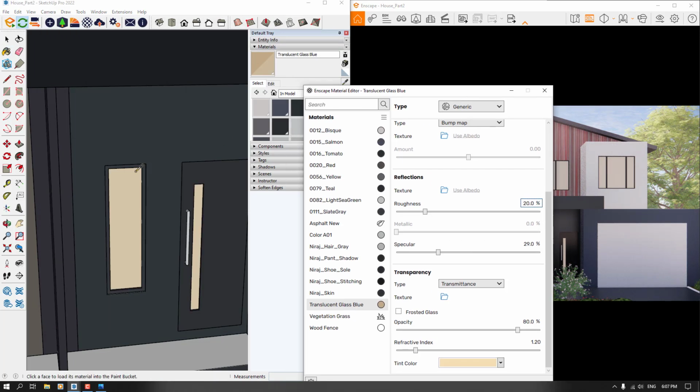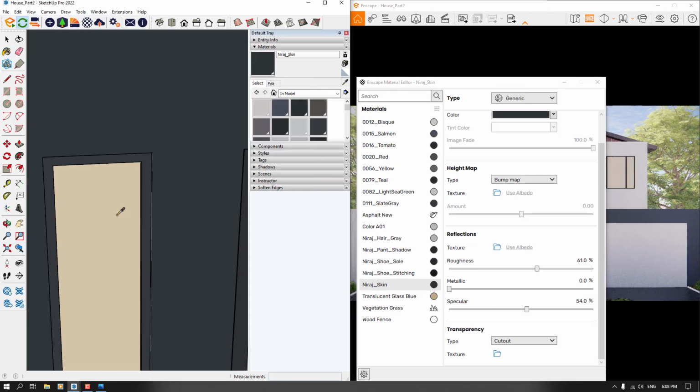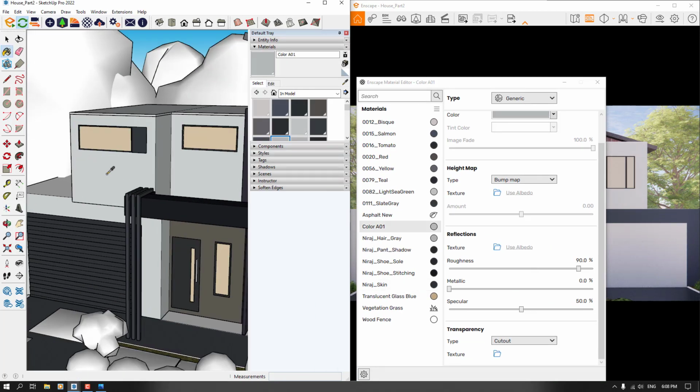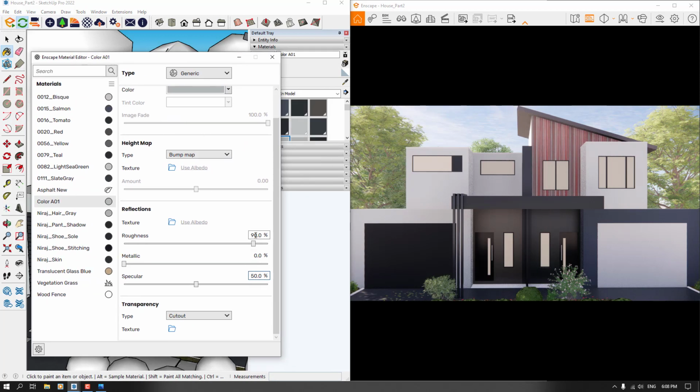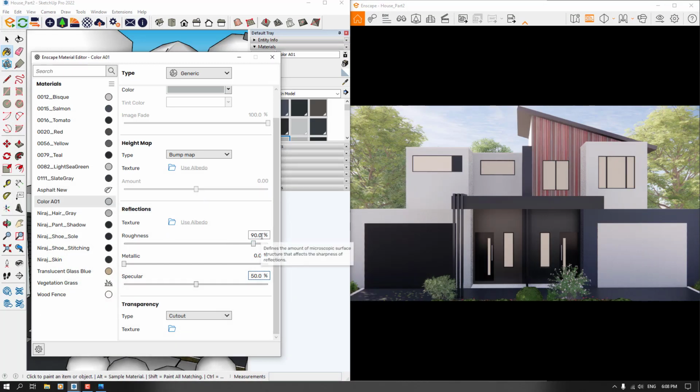Okay, go to the window frames. I'm gonna select them and decrease the roughness to about 61. Okay, not bad, 54. I come to the walls. As you can see, I click on it. Now we have this color set and material adjustment. I'm gonna reduce the roughness. These materials have a little bit of reflection of the sunlight, so I'm gonna decrease it to about 71, like it, much better.